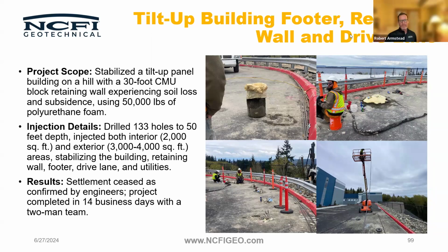I mean, that's the main point, right? And it's the main point of stabilization as well. Gridded patterns may have some sort of layers in between, but it's really still compacting and compressing those soils. The more you're doing as far as your grid pattern, from a horizontal grid pattern, that X and Y scenario, the more saturation you're going to get, the more compression you're going to get between your individual grout columns. So it can really create a watertight seal that's heavy. But again, soil types can play a factor in that.